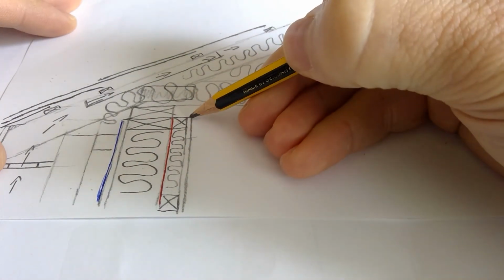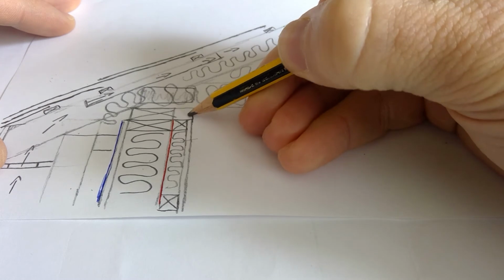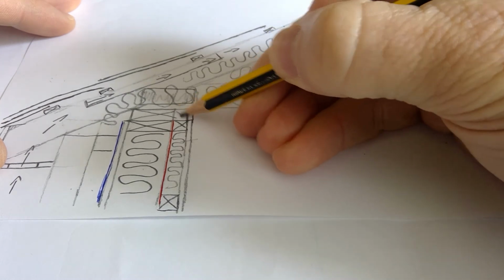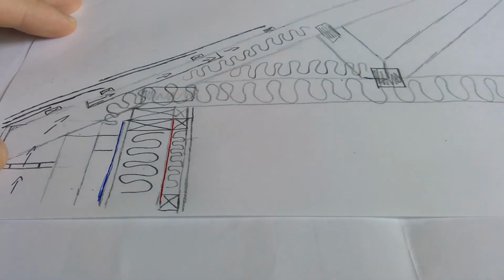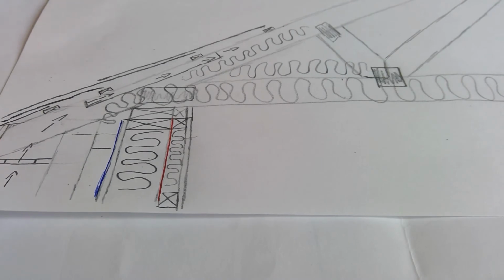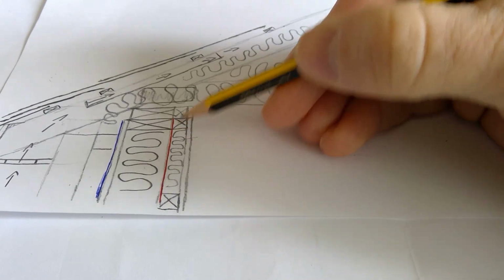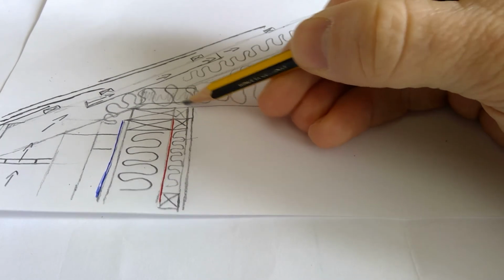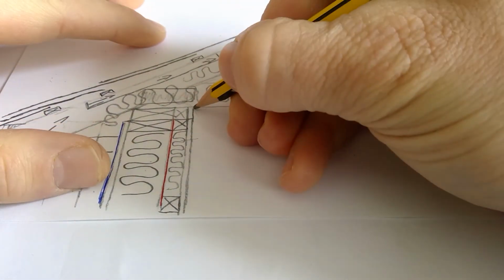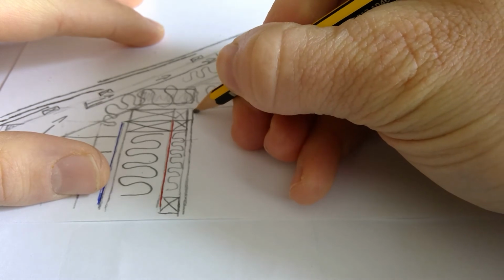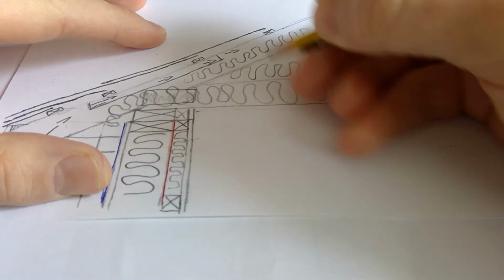I've just noticed my service cavity that actually needs to go right to the top. So let me put that batten up there, and that's the majority of it done. Part B, it asks to show how it's airtight at the ceiling and the wall, so how no air is stopped from leaking out through this junction here. What you would do is you could put some plasterboard on the ceiling.